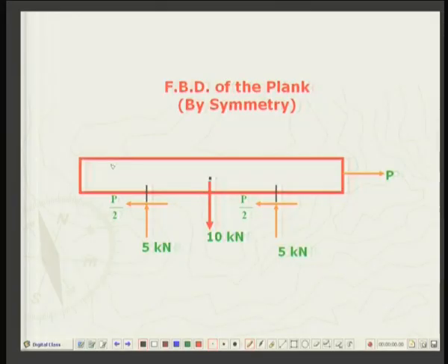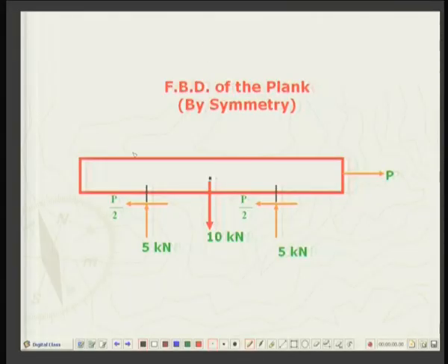First of all, let us look at the free body of the plank. This is the plank which is being pulled by a force of P. Now here we will invoke the argument of symmetry. The two rollers are placed symmetrically, or they are supporting the plank symmetrically. The total weight of the plank is acting through the center, 10 kilonewton. So due to symmetry of the loading as well as symmetry of the geometry, it is quite obvious that the reactions will also be equal.